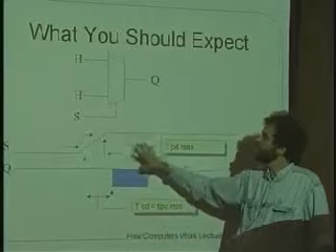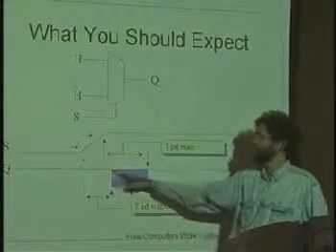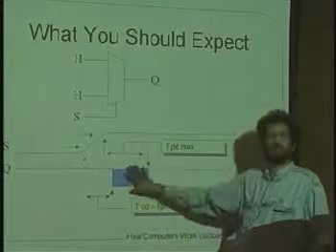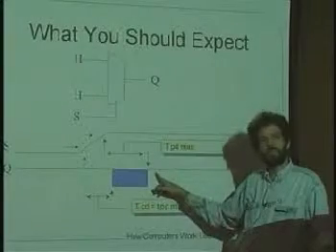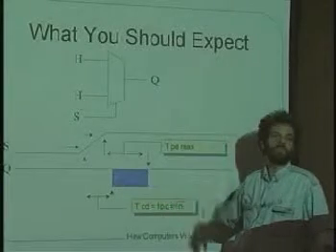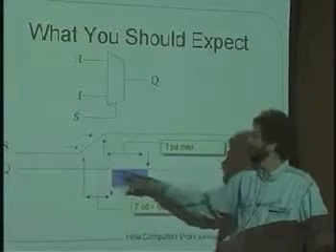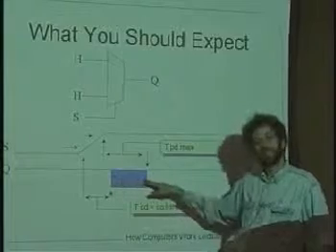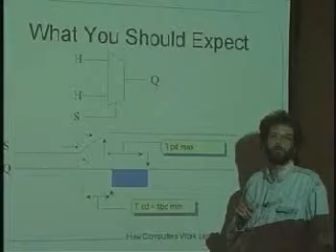If we were given the specifications for the device in terms of TCD and TPD, what that would say is if a hazard is going to take place, it'll happen somewhere during this blue time here. And so that's what the meaning of the difference between when the TCD is up and when the TPD is up. That during this time on the output, kind of all bets are off. We don't know what the output is going to be, because we only guarantee that we'll hold on to the old value of Q up to here, and we only guarantee that we'll start putting out the new value of Q over here. And in between those two times, in general, in logic circuits, we don't guarantee anything at all.